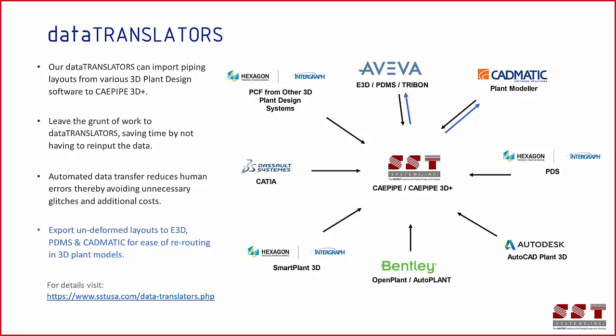Again, the data translators are built into CAEPIPE3D+. You have the interfaces from E3D, PDMS, Tribon from Aveva. CADmatic model can be brought in, PDS and Smart Plant 3D coming from Hexagon, and Autodesk Plant 3D, Bentley's 3D model, as well as a number of software like SolidWorks, Solid Edge. They produce what is called a PCF file. PCF stands for piping component file, so that piping component file can be brought into CAEPIPE as well as CAEPIPE3D+.